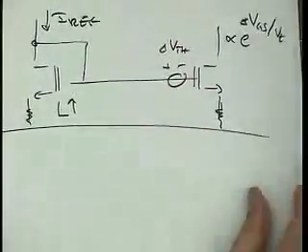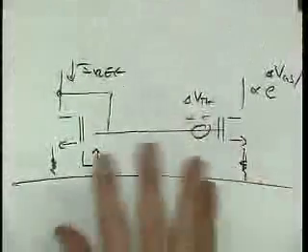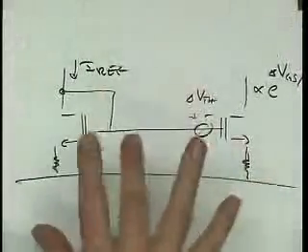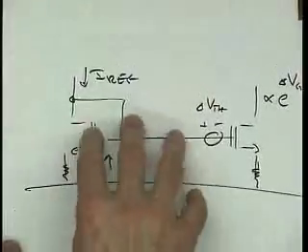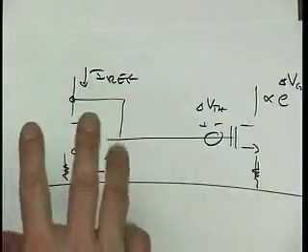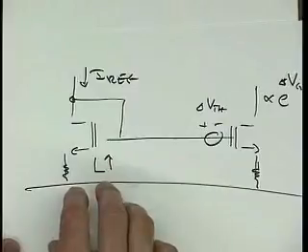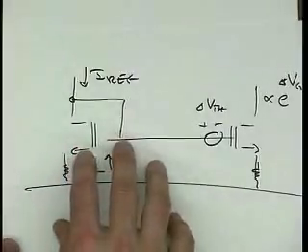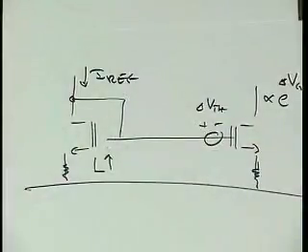If this was to actually run the signal through, well, then it might not be such a good idea, so maybe a compromise. Okay, so nothing is totally for free, but you can be a little bit careful. But we can exploit this, and so often what we will do is we make VGS very small in a diff pair to get reasonably close to weak inversion, and so have high gm transistors, right? And in our current mirrors, well, we make L big so that we are far from weak inversion.